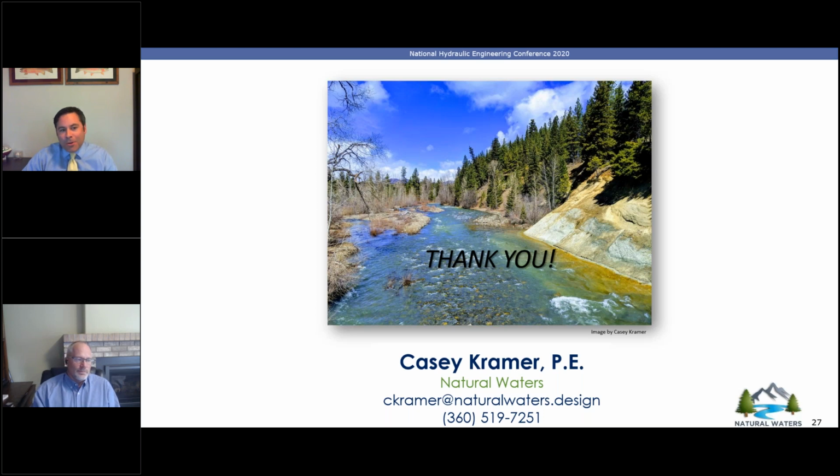Yeah, early coordination with your survey team is instrumental. We were super fortunate to work with the WSDOT survey crew. They're some of the best in the business, in my opinion, not only for collecting the data efficiently, but also collaborating. This case study is an example of that, where almost all of the topo data outside of the channel was from existing LiDAR. Rather than resurveying all that, they would just go in and take transects to verify that they were okay with the results of the LiDAR.